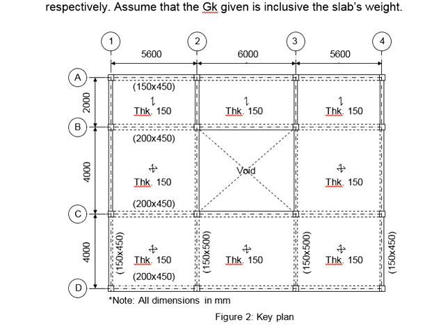Now when the slab and the beam are well intact, that means the beam can be used to restrain the deflections of the slab. The longer span will have a stronger resistance or restraint to the slab, preventing it from undergoing excessive deflection, whereas for the shorter span, the restraint is not as significant as compared to the longer span.